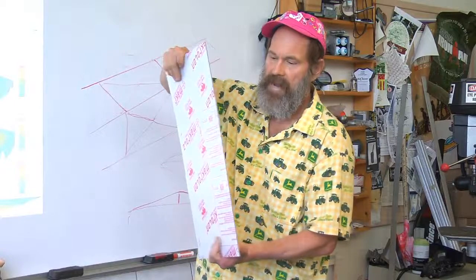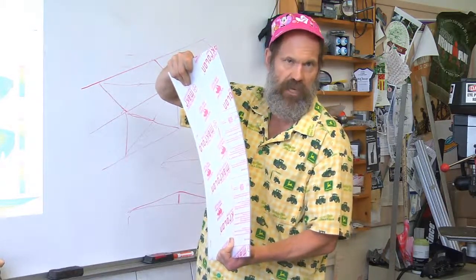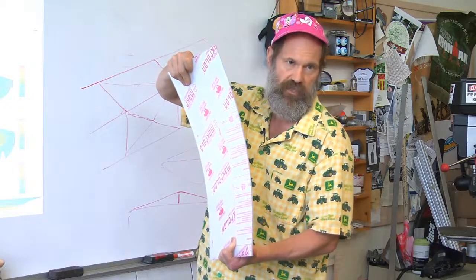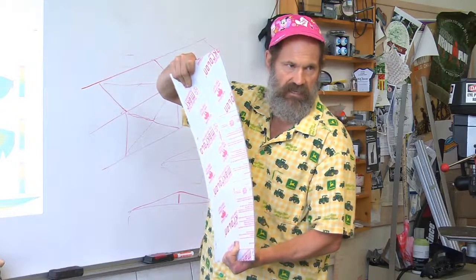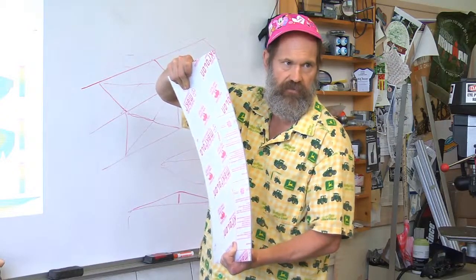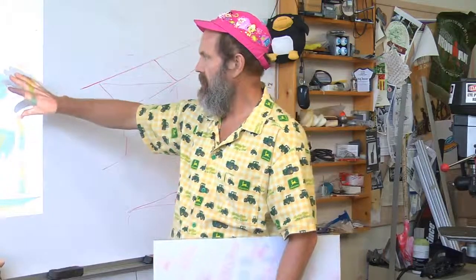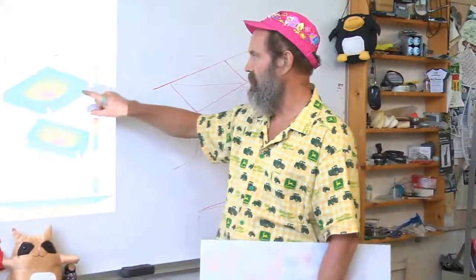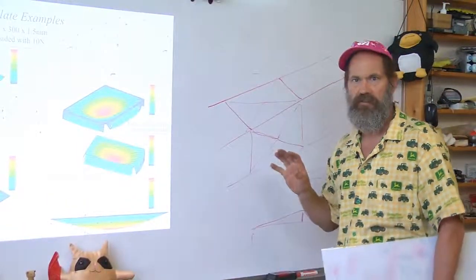You often want to bias things in one direction or the other, toward the particular mode shape that you're trying to quench or stop, and leave it there. Now it's much, much more stable and stiff. So you can discover that doing your finite element analysis, looking at adding ribs or pre-displacing structures to get a very much higher degree of stiffness.